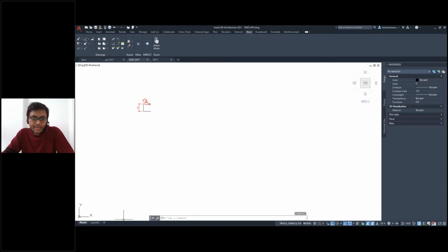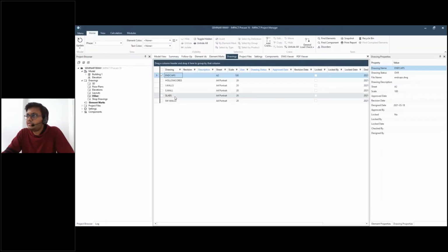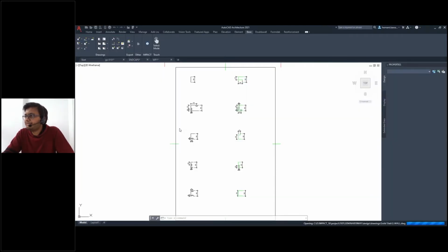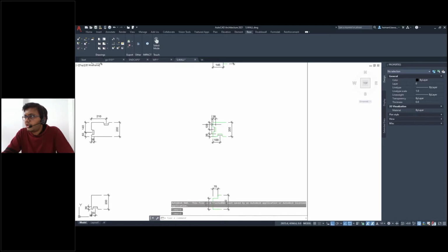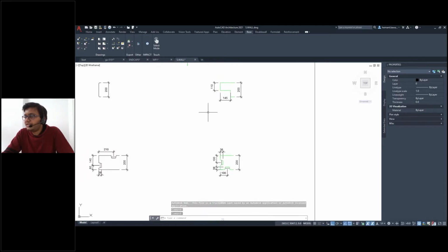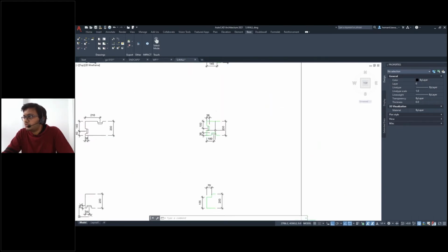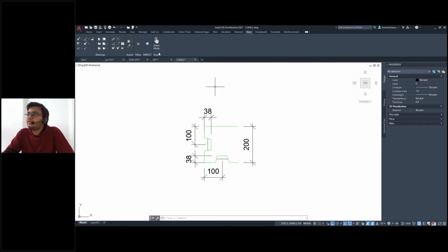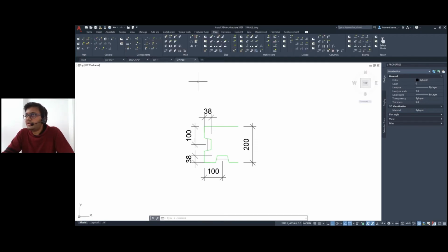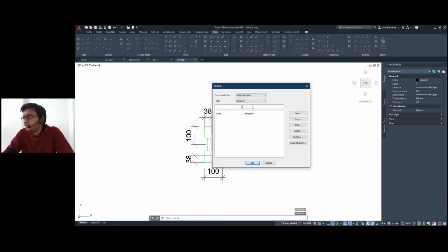Now to save some time, I have created some of the geometries. I will just open those up. As you can see, we can add multiple geometries at the end of the wall and they will be available. So we will quickly define this end cap. Go into the plan, go into the end cap and create a new one.